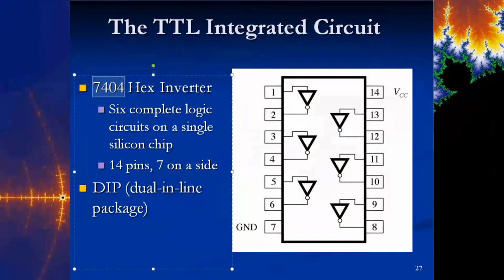Sometimes it's not always in this orientation where 1 is always an input. Sometimes it's backwards, and maybe 2 is an input and 1 is the output. That's why it's so important to have the pinout. Otherwise, there's no way you're ever going to know where to put your inputs and outputs because there is no marking on it. The only marking on it is what the model number is. Okay? Any questions? Okay, you guys are stuck with me pretty good here.